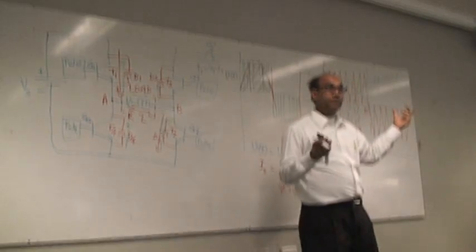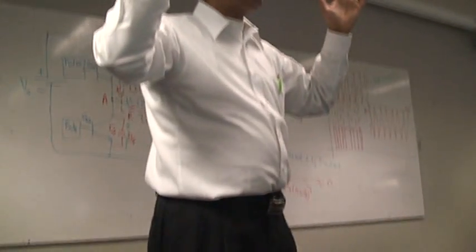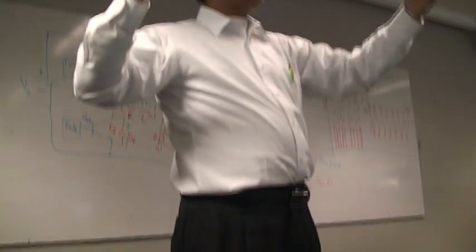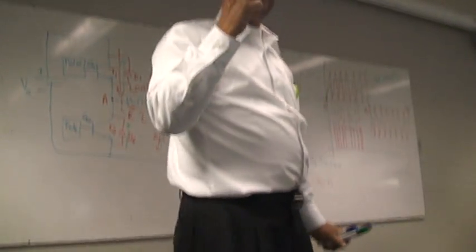One of the problems for the software is that even though you say the angle remains the same, 360 degree for a period, when you think of the frequency, at 50 Hertz your time period becomes 20 milliseconds. If you make it 40 Hertz, your time period becomes 25 milliseconds. So when you write that code in a microcontroller, you cannot give the angle, you have to give the time. So making that time is a little bit difficult.